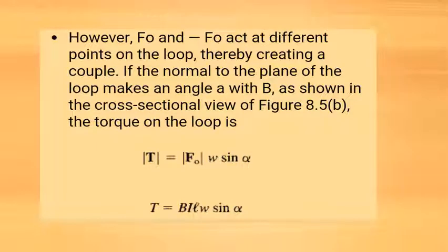The torque can be written as F into W sin alpha, which is from the figure. Substitute the value of force in the above equation, and you get torque T equal to BIL W sin alpha. The BIL is the value of force.